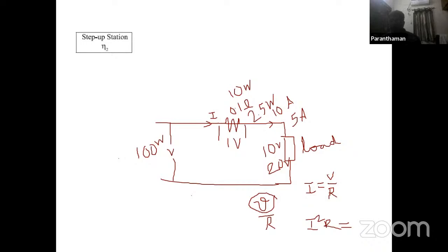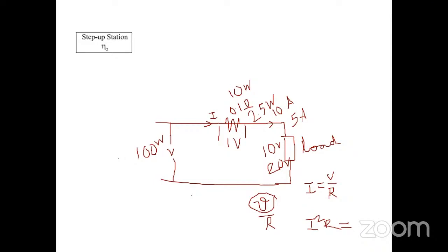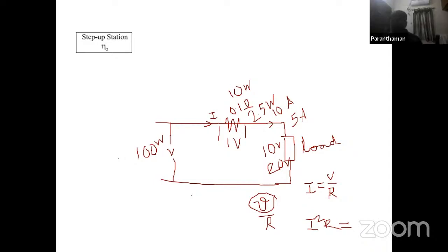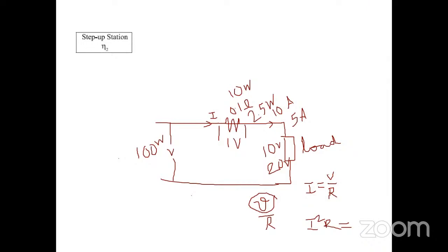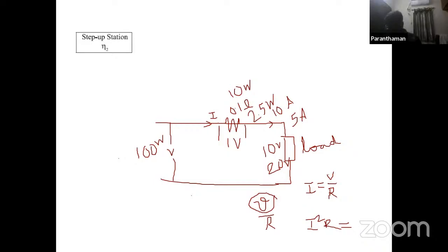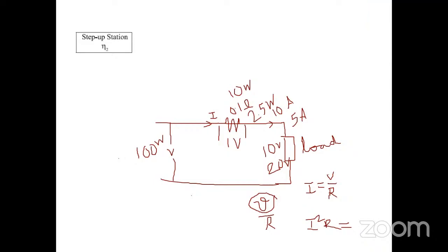There is one step up transformer. That will be raising the voltage to 400 kV. That is the generator transformer. The generator transformer is the first place losing energy. What is that percentage? It is the most efficient of all equipment in the power station. Correct, 99.5% for transformers.